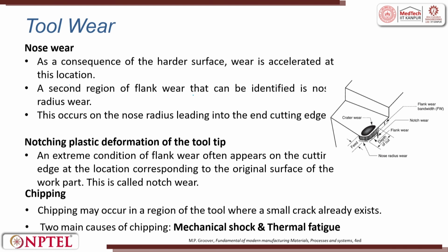The second region of flank wear can be identified at the nose radius. So, here: flank, nose, crater. It is very difficult to measure, so we always try to measure the average points. There is notching and plastic deformation which happens on the tool tip. Extreme conditions of flank wear often appear on the cutting edge at the location corresponding to the original workpiece surface. There is also a possibility of chipping of the tool when the forces are very high.